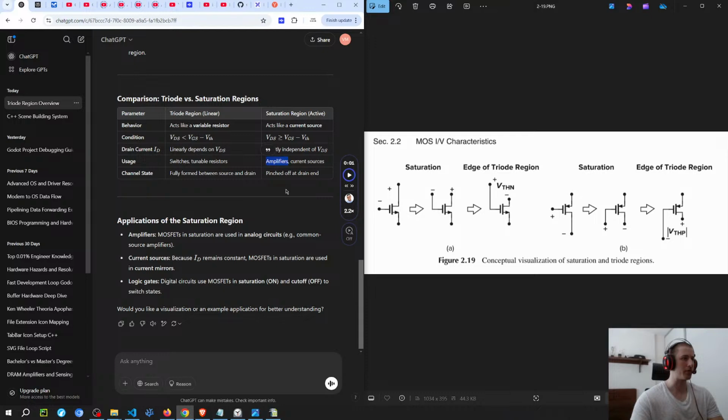And these amplifiers I remember from the DRAM lectures, Onur Mutlu's lectures, or I think it's in the flash memory lessons. So you have an amplifier at the bottom of the memory bank. Based on the signal, when you read the row, you disturb the signal of the row. Then you use the amplifier to amplify the signal, because it's a very small signal on the capacitance. Then it amplifies it to get a clear one or zero, and then the amplifier has a circuitry that goes back to the row to refresh the row.